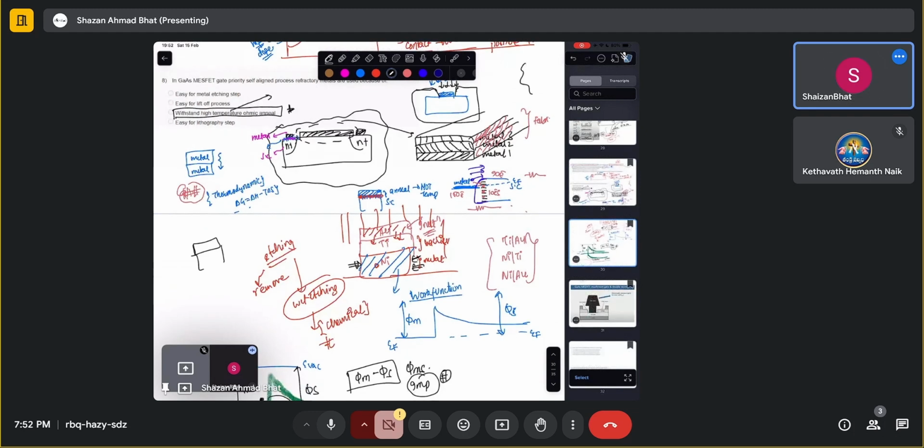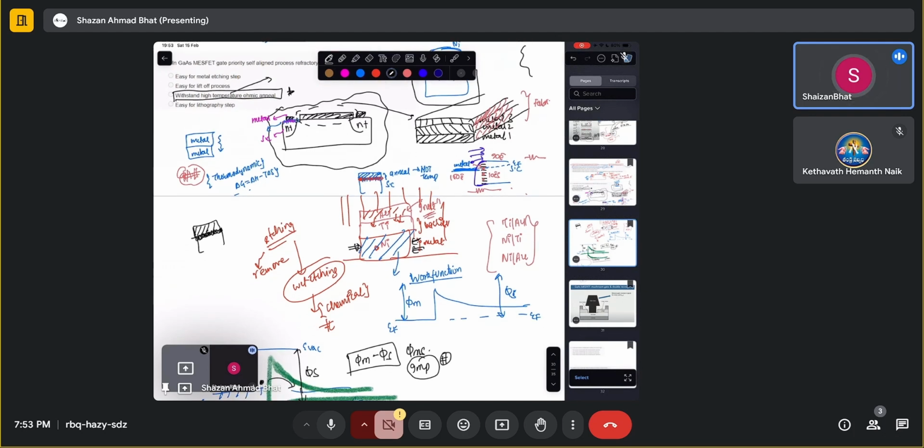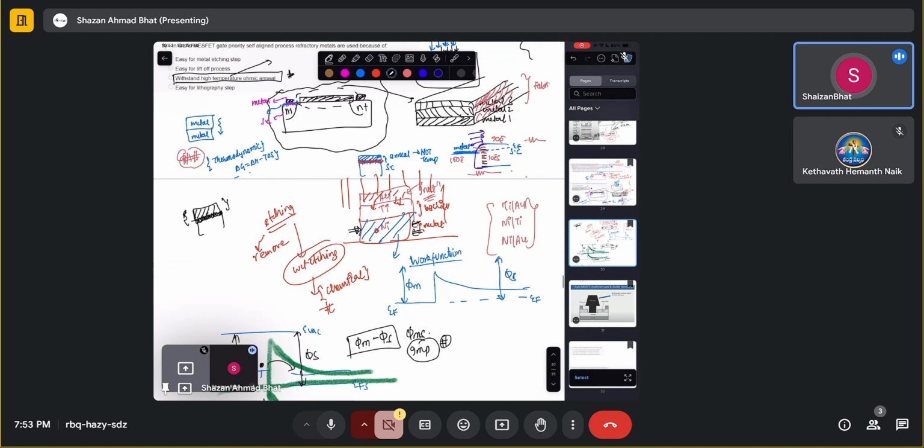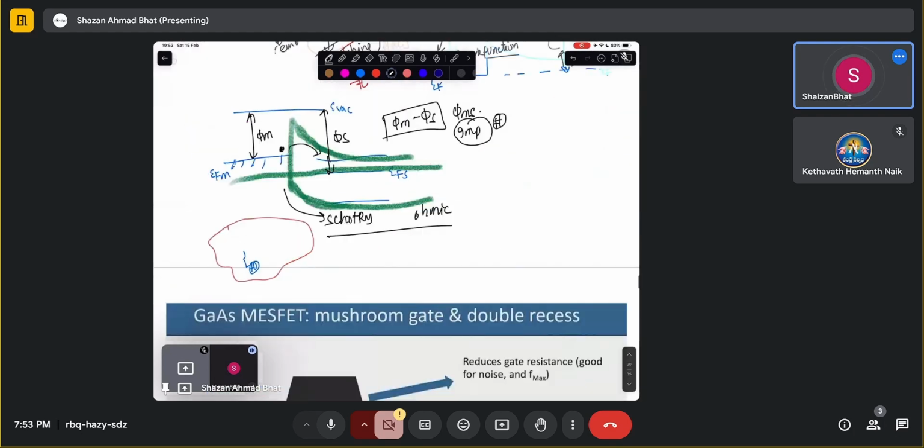If you want to anneal the metal and make a diffuser more towards the semiconductor, then you want it to withstand a higher temperature, of the order of, maybe I don't remember the exact value, 1000 Kelvin or maybe 500 Kelvin. Then it can withstand that temperature better. Otherwise, what will happen if you heat it a lot more? It's going to melt or rather diffuse a lot into it and totally destroy the semiconductor, and the contact will be poor. So that is the important point here. But it will also be important if you want to protect it from certain chemicals. That's also going to be important.